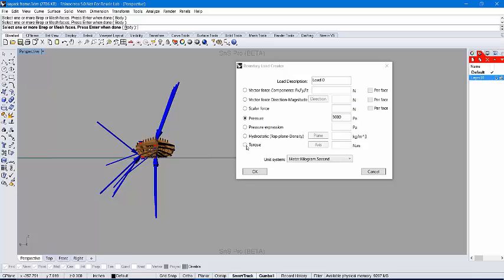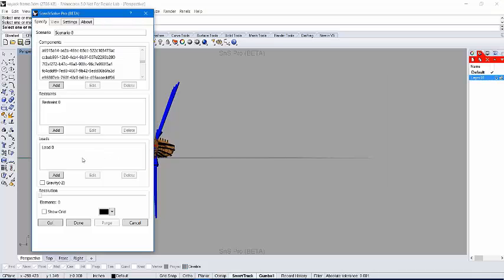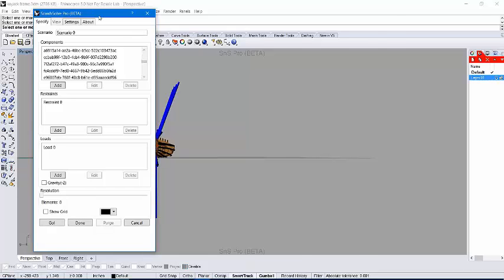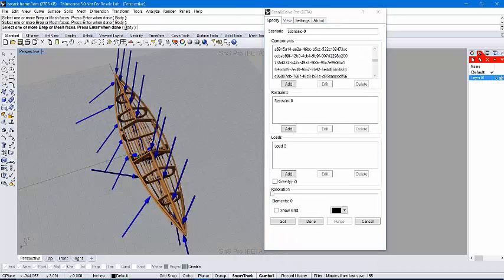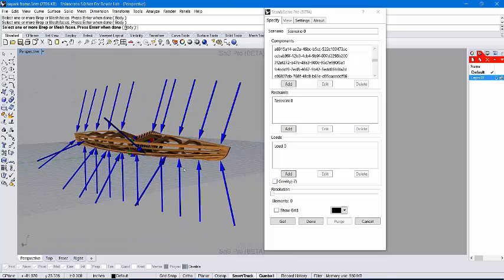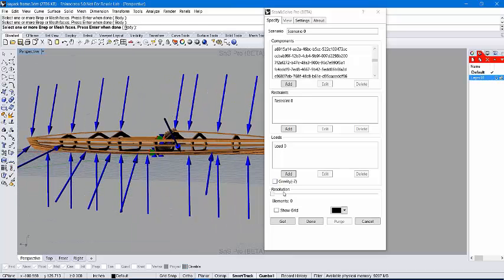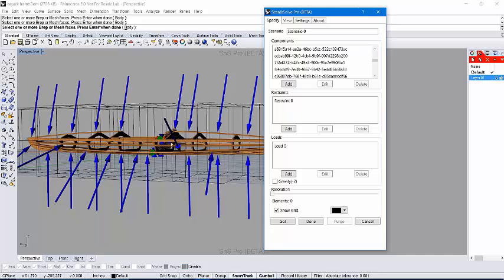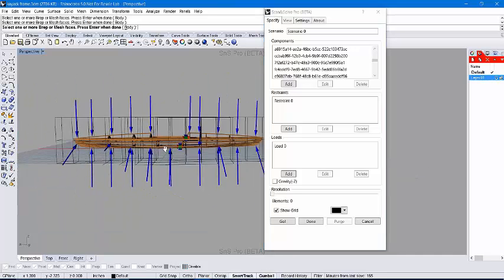This load is ready, properly set up. So the kayak is almost ready to simulate. Once again, I'm going to leave gravity out. It should play a pretty minimal effect. Just a few last things to touch base on. The resolution. Once again, we now know we want about 3 of these elements per cross-sectional area, and we're pretty far from that. So let's see what this looks like.